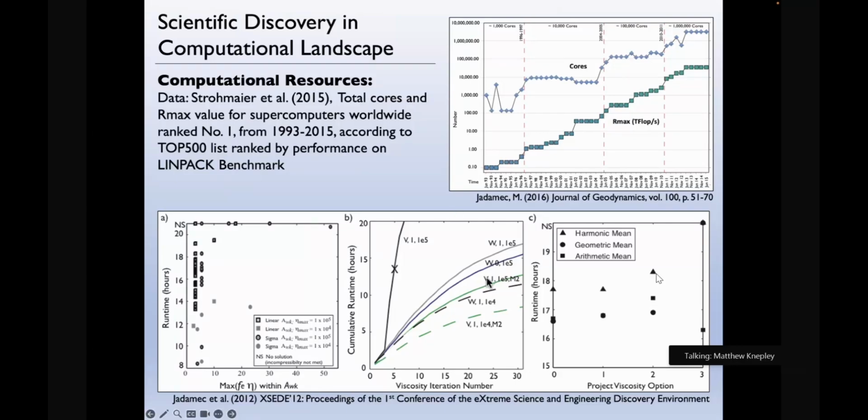And you can see that depending upon whether you're using V cycle or W cycle, your overall viscosity bounds in the model, how you project or average the viscosity between levels in the multigrid, and your resolution, those can all have a significant effect on runtime, from 0 hours to 15, to some of them having no solution and not converging. So in addition to just having the cores, you need to get the algorithms right, or optimize them, because it can have a huge impact on the runtime. As you all know, I'm preaching to the choir here.